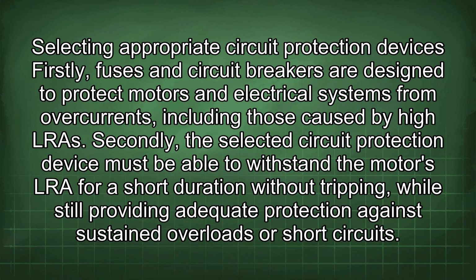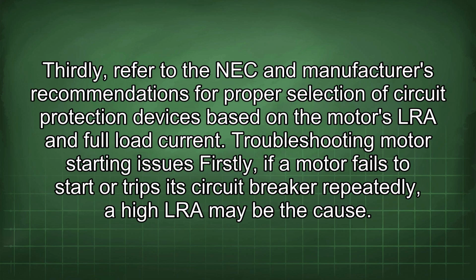Firstly, fuses and circuit breakers are designed to protect motors and electrical systems from overcurrents, including those caused by high LRA. Secondly, the selected circuit protection device must be able to withstand the motor's LRA for a short duration without tripping, while still providing adequate protection against sustained overloads or short circuits. Thirdly, refer to the NEC and manufacturer's recommendations for proper selection of circuit protection devices based on the motor's LRA and full load current. Troubleshooting motor starting issues.